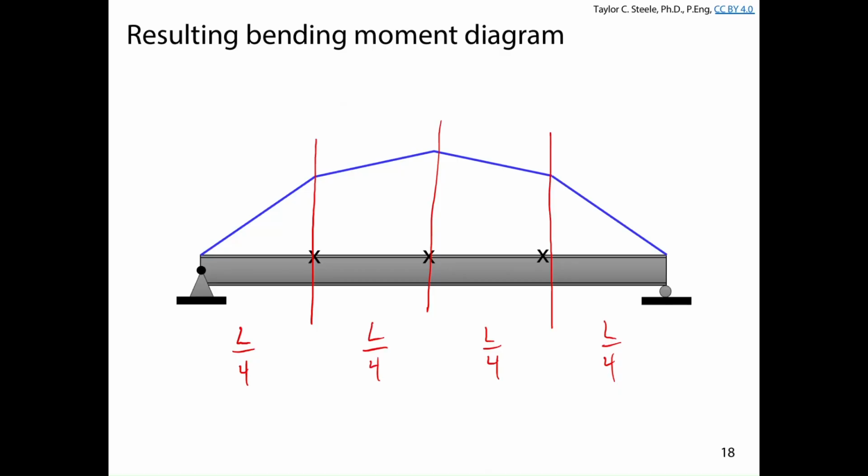Well, this is slightly different from what we looked at previously. Over here, we've got a segment with M1 is 0 and M2 is some value. Basically what we've got here is we have a moment, and actually at these other locations, if you were to draw the bending moment diagram, these work out to 0.75 times the maximum moment. And so on the left-hand side, we have a segment with 75% of the maximum moment on the section.